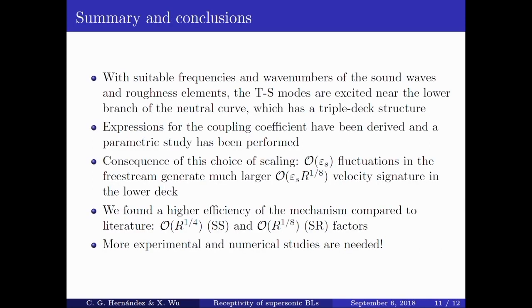So as a summary, with suitable frequencies and wave numbers of the sound waves and roughness elements, the TS modes are excited near the lower branch of the neutral curve, which has a triple deck structure. Expressions for the coupling coefficient have been derived and a parametric study has been performed.